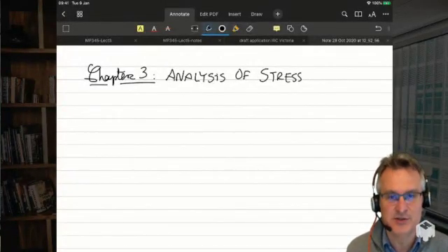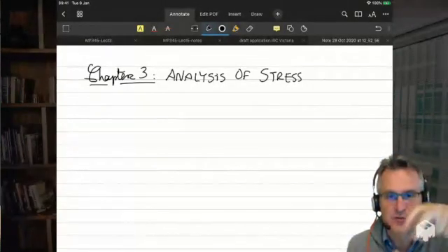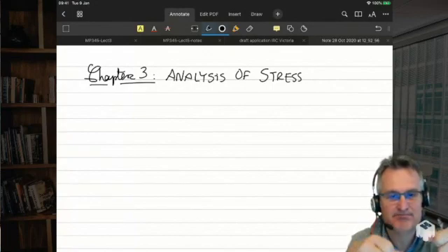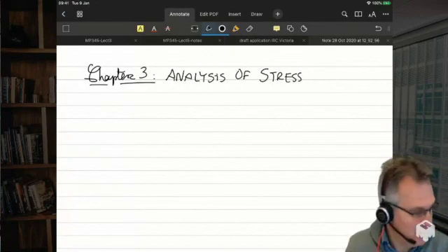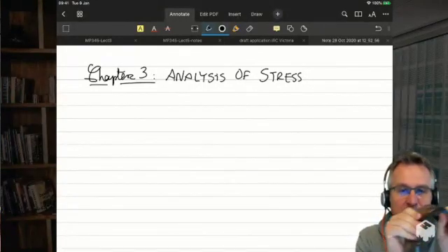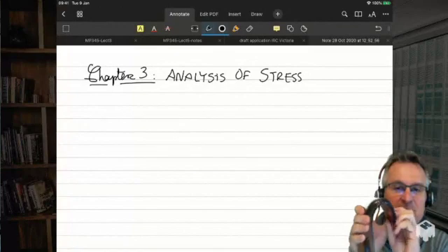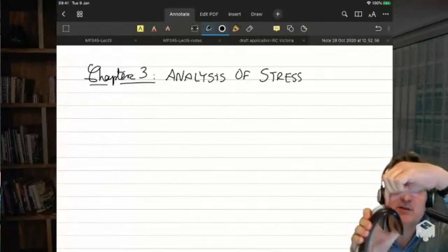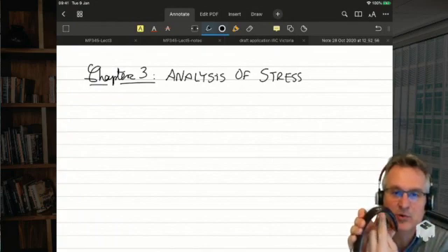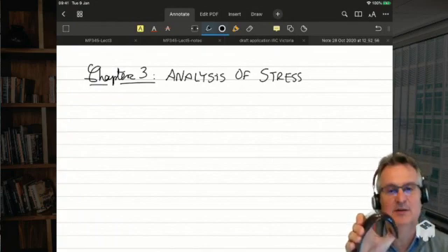If it's inhomogeneous, think for instance of torsion. If you do torsion or bending, right? If you're bending a block, yeah, I might bend this block. Oops, like this. You can imagine that little elements on this surface are stretched a lot, whereas little elements on the bottom ones are contracted a lot.